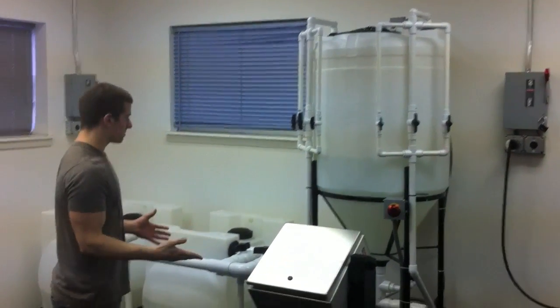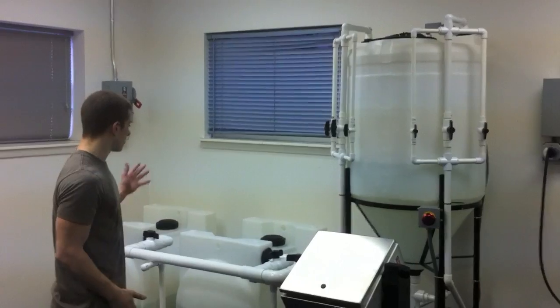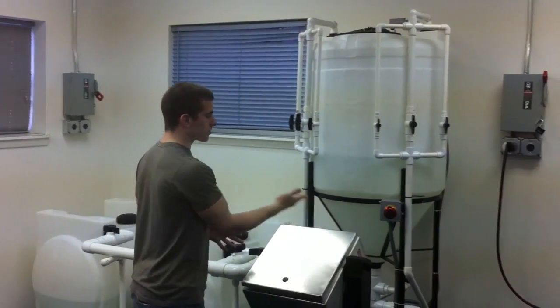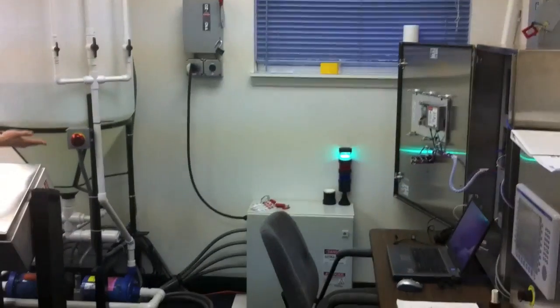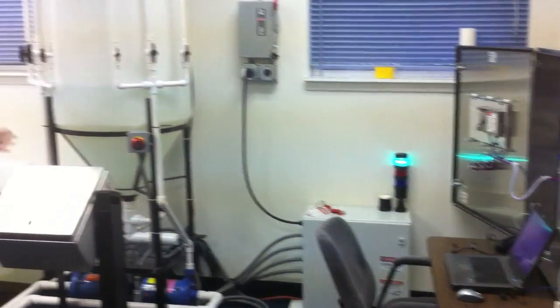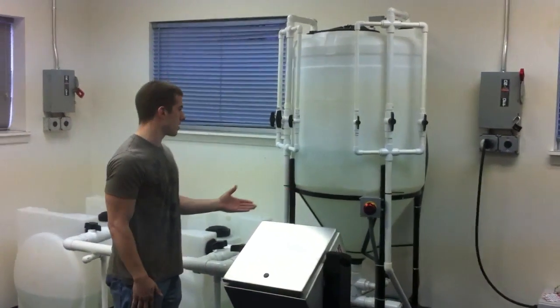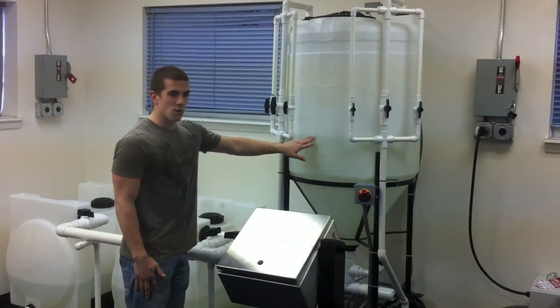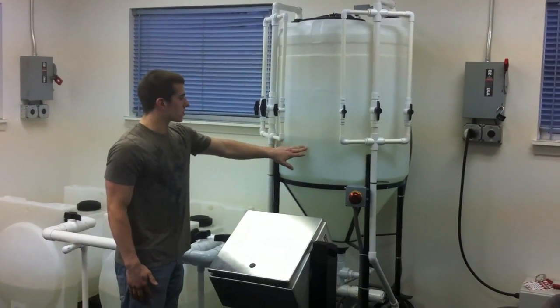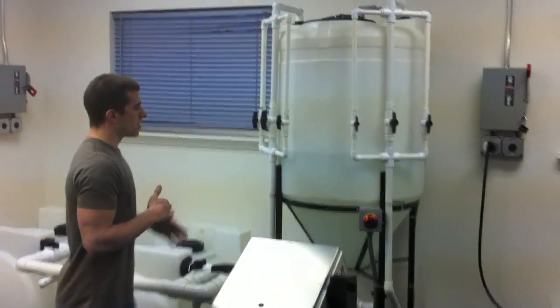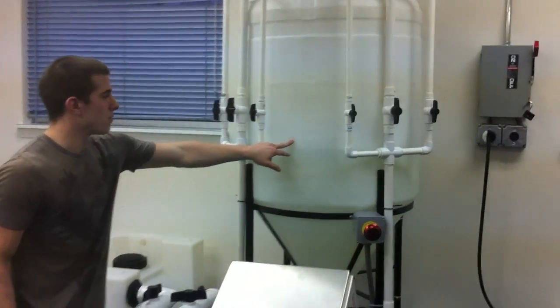This is the physical system of the senior design project that we built, the plumbing and the electrical side of things, and the pumps over there and our enclosure over there. On top of our 480 volt enclosure, we have the stack light indicating the state of the system, which is currently green for go. You can see the water level right now is at 45 gallons, which started at 40 gallons. So right now we're just letting it ramp up to the 50 gallon set point.